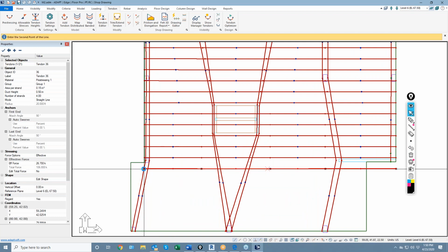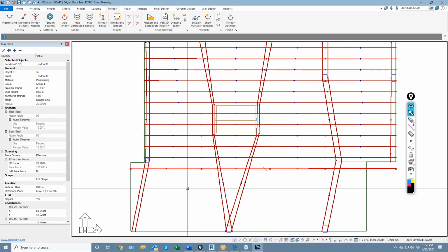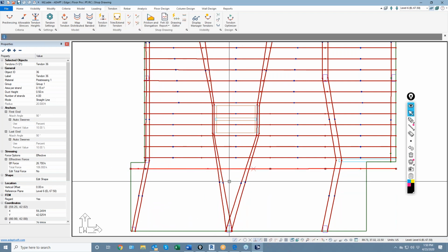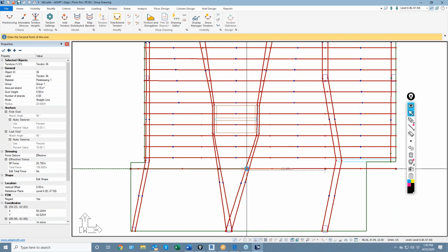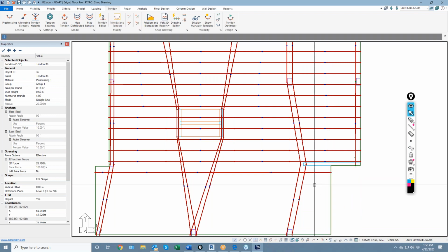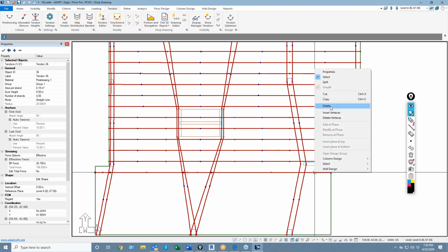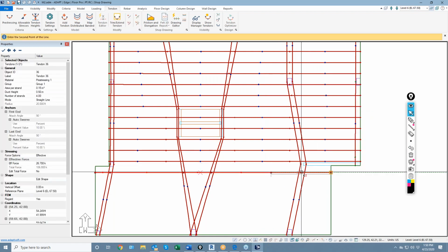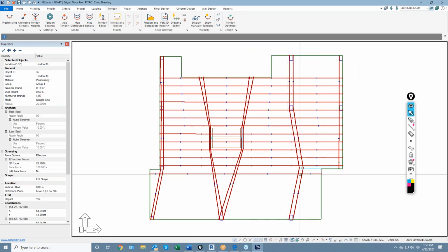Okay, let's go ahead and adjust, see if we can get through these cables. Let me model. I'm going to move these points over. I'll just move this over. I'll use this as another primary tendon that I'm manipulating now. Let me save the file. I'm going to right click, insert a point right there and just move it over. So this is a new high point.